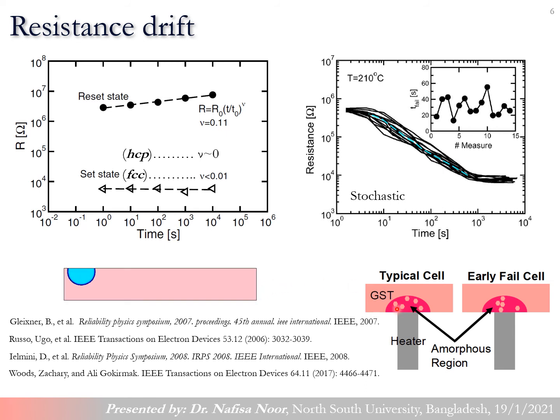Now, this nucleation of different islands can be at different locations and at different times, even when we cycle the same cell during the crystallization of the different cycles. So because of these variations in their locations and the timing of their popping up, we can have different decreases of resistance over time, and that is why we have different trajectories for the spontaneous data loss trend in the PCM.